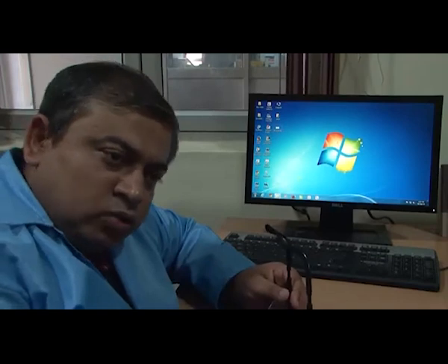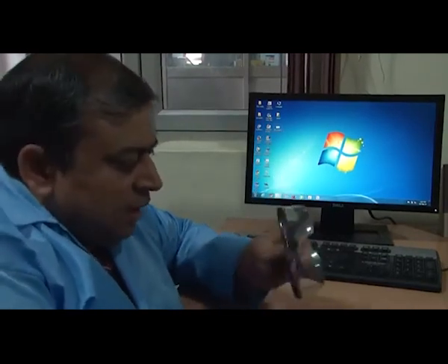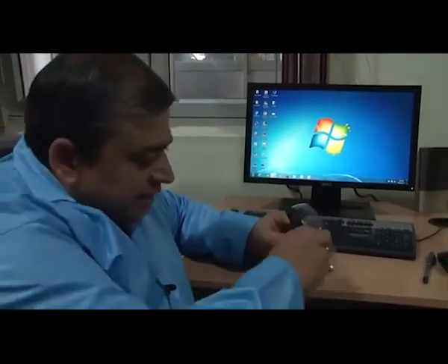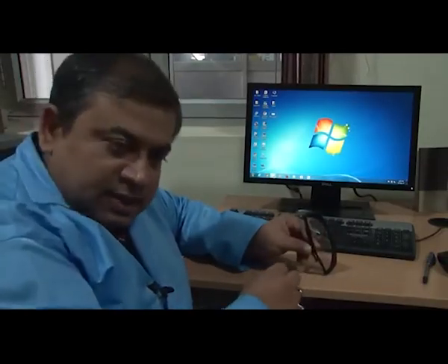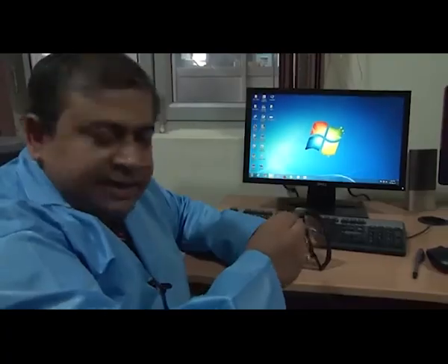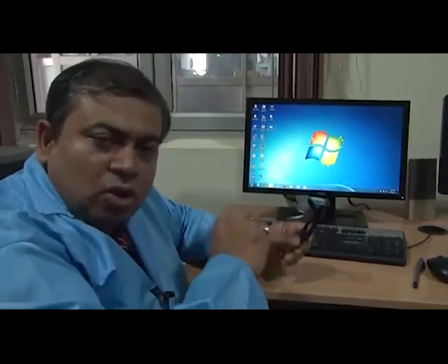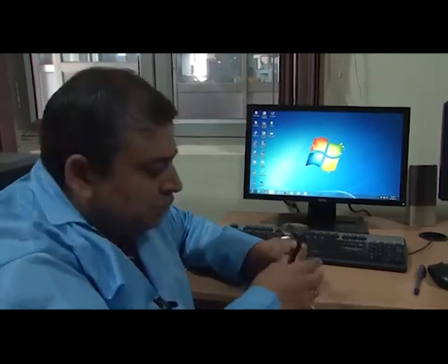That is number one. Number two, there is a huge issue: supposing this is a part that we want to manufacture using RP, we'll have to somehow suspend it using supports so that the whole part can be fabricated. The question is how the support should be kept in a minimalistic manner, so that later it can be cleaved. There can be a parting line from which the main object can be separated from the support, and the support is the most hollow part with as little material as possible, in comparison to the object, which is more solid in nature.